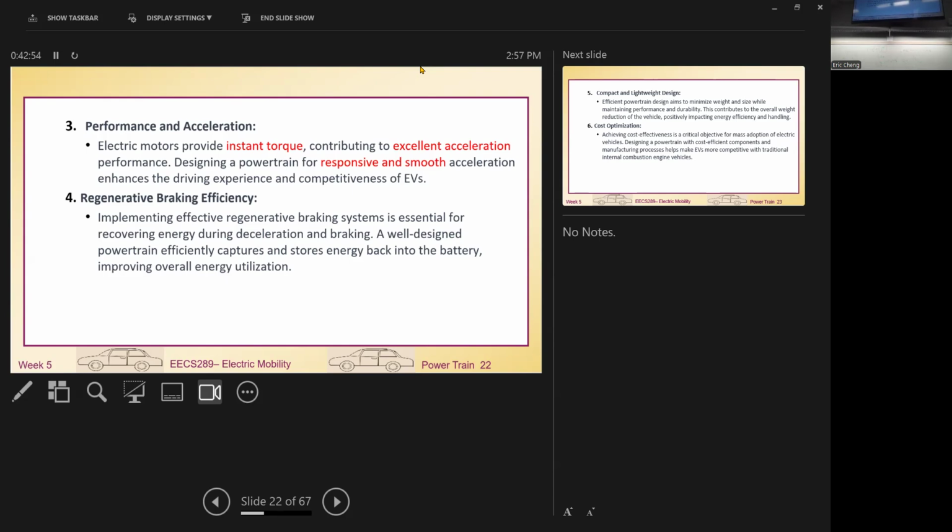Just like when we designed the SR motor just now, with motoring and then regeneration. For motoring, we can design really nice motoring, but we can also design the regeneration perfectly well for the inductance profile. So we can't have perfect for both ends. So motor design will be like that. We need to try a system so that power regeneration is also good, but we can't make both motoring and regeneration perfectly good.